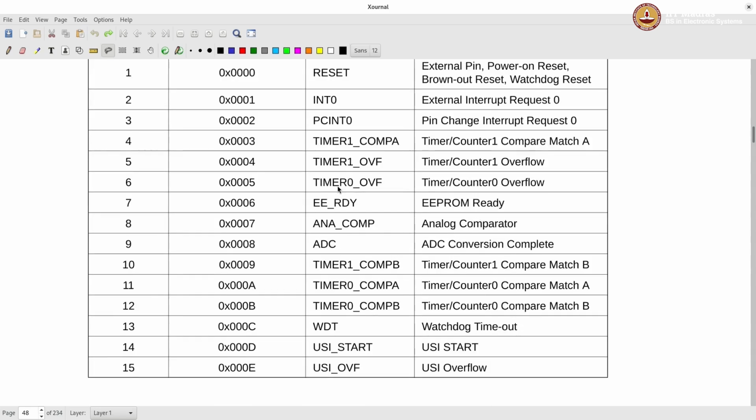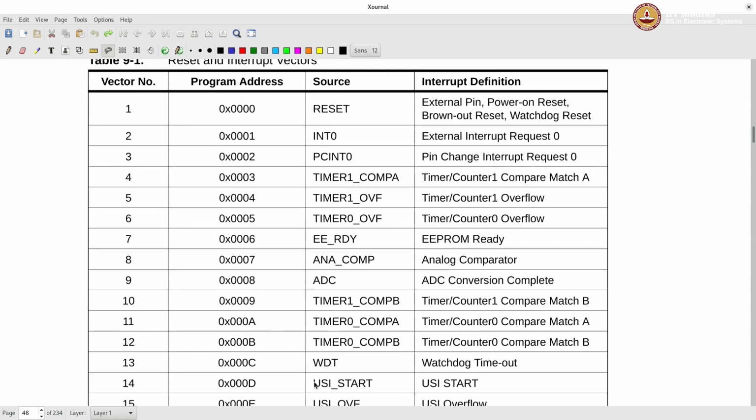Okay. So you need to have an ISR opened for each of these, except the reset, and close it by having a return, or in the assembly giving a no operation, so that if there are any spurious interrupts happening, it will not just go and hang at some point until you go and press the reset, where the program counter will go back again to the main program.